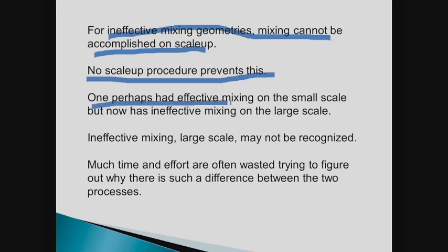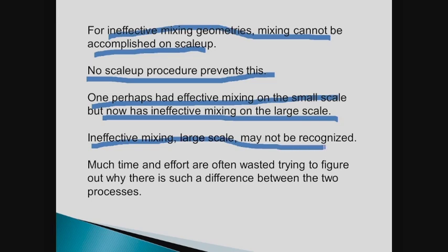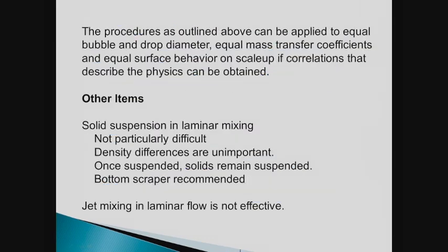Ineffective mixing geometries. Mixing can't be accomplished on scale-up. No scale-up procedure prevents this. One perhaps had effective mixing on the small scale, and now has ineffective mixing on the large scale. Ineffective mixing on the large scale may not be recognized. Much time and effort are wasted trying to figure out why there's such a difference between the two processes. Well, it's just they're different processes. So the procedures outlined above can be applied.